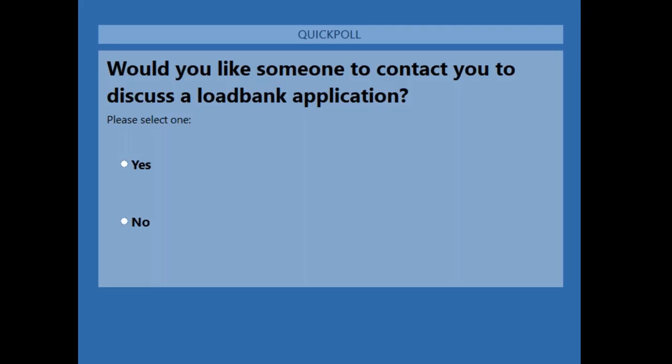is when it goes away from a factory housing and now it's into a walk-in enclosure. We can't determine that, but if you're specifying it as a walk-in style, custom enclosure, then it will be a duct-mounted load bank packaged inside the genset. If you don't specify, then the generator provider will probably pick the factory housing because it's cheaper. There's nothing wrong with it. It's a great enclosure, and then we would provide it as a rooftop at that point.